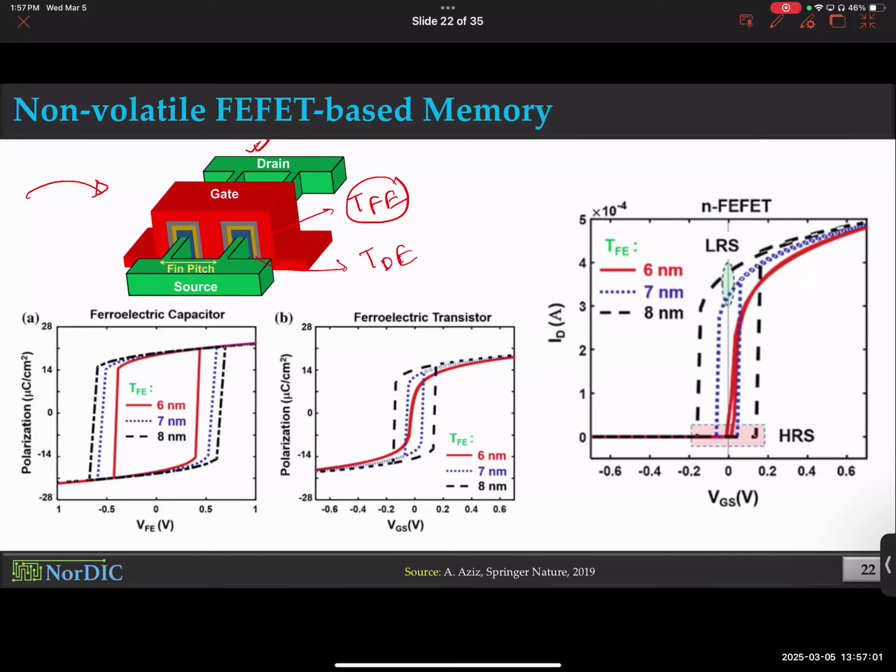So if you have PZT as ferroelectric, underneath there could be hafnium oxide as well. So you always have a conventional oxide, and then on top of it, you have ferroelectric oxide in the transistor. So the relative thickness matters. But we could always decide to just keep the dielectric thickness constant and only tune the ferroelectric thickness. That works too.